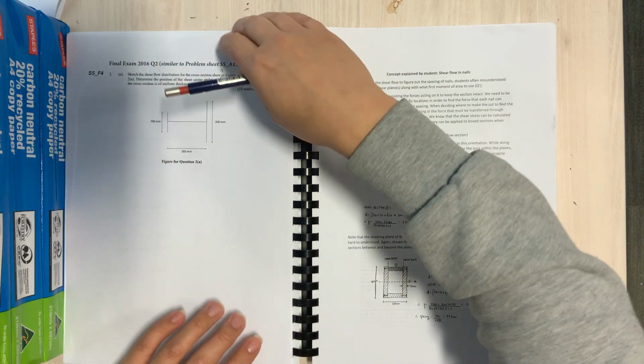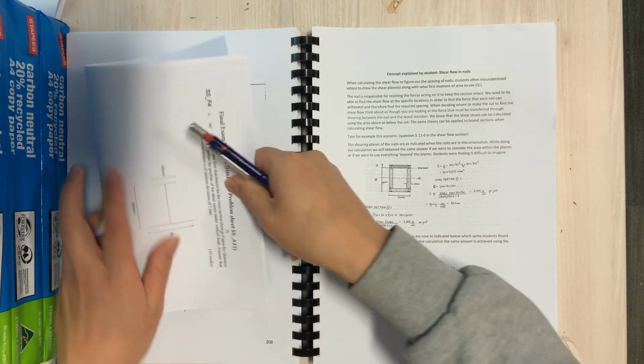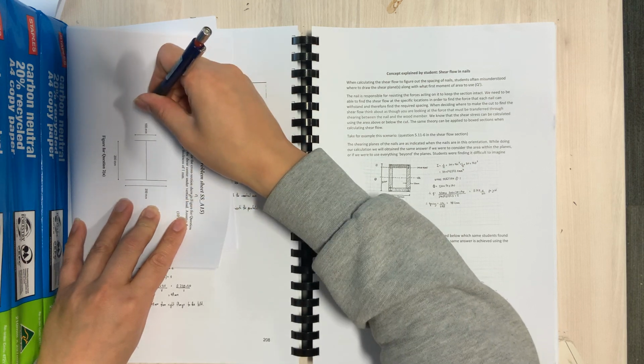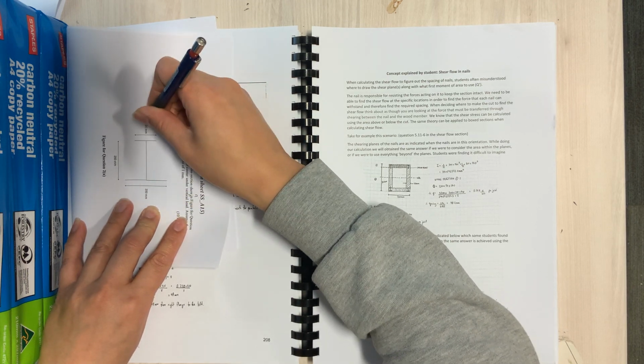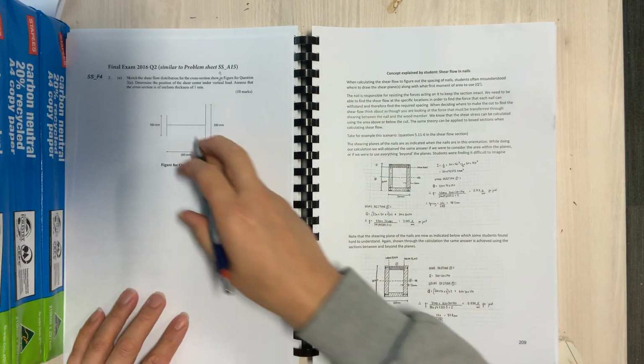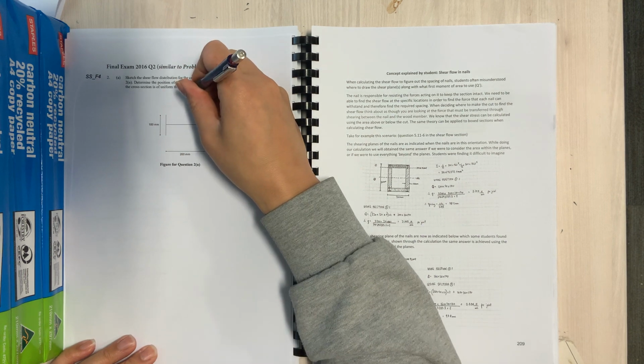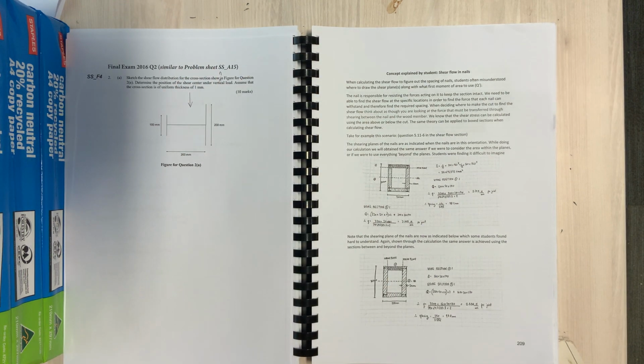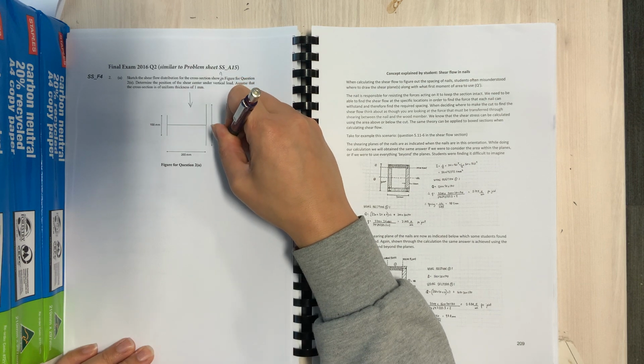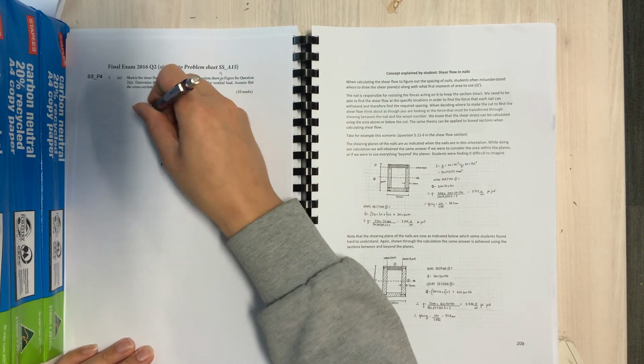So when the section was this way around, then we know that the shear center is going to be down there. But what happens when the section is rotated round? We've now got to calculate the position of the shear center. So go back to what we've already said, is that we've got some load coming down here into the section, and there's going to be some horizontal shear flow maybe, and there's going to be some vertical shear stresses or shear flow.